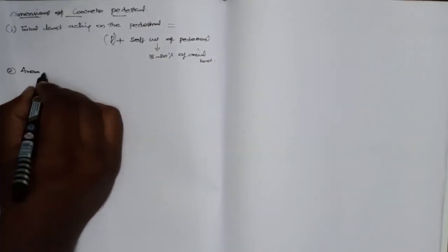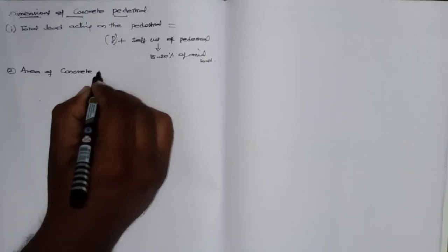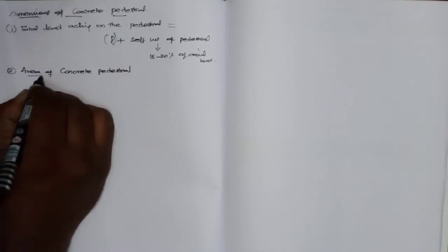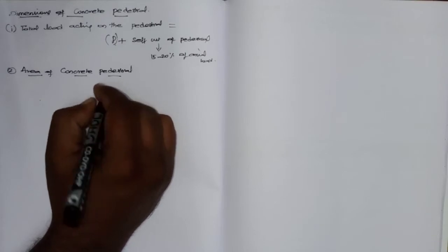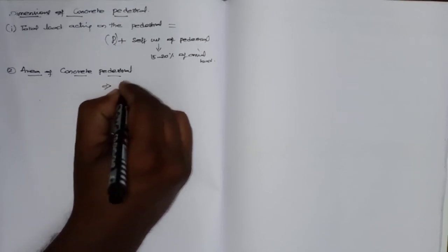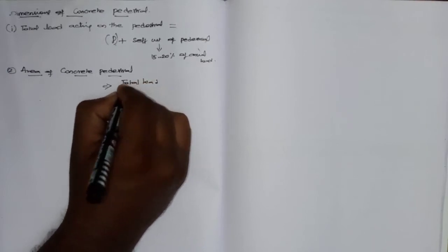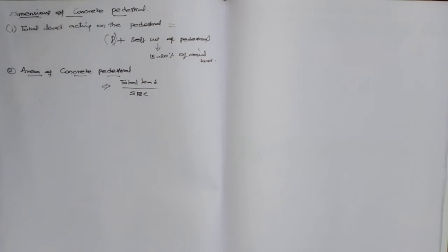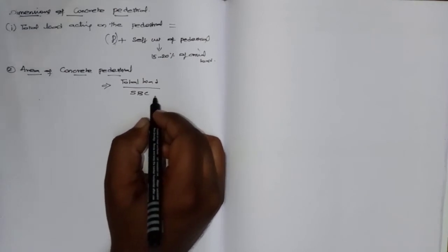Next, the area of concrete pedestal is nothing but the total load by SBC of soil. What is this SBC? Safe bearing capacity of soil.